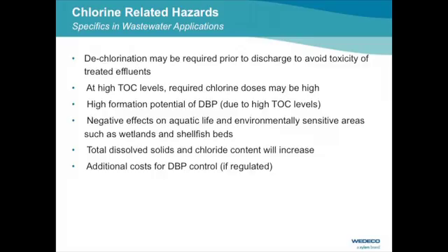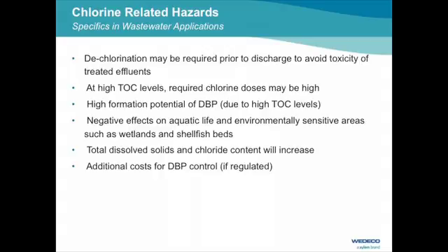Then there are a few specific points I would like to highlight when it comes to disinfection of wastewater. Here we typically have particularly high TOC levels, and that enhances the formation of those undesired disinfection byproducts. Additionally, you need to dose quite a bit of chlorine because it's oxidizing whatever there is in the water. If you have a lot of organic matter, you also need to dose high levels of chlorine.